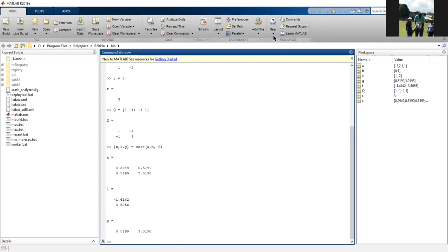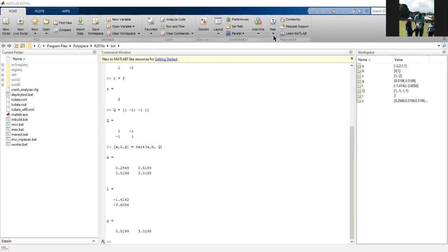All right. So the part that was missing was the Q, the gains of the system. That wasn't in the example. So these are the two gains that we would use. What they gave us was the eigenvalues of the old matrix, and that wasn't stable, and then the eigenvalues of the new matrix when you apply the gains to the system.